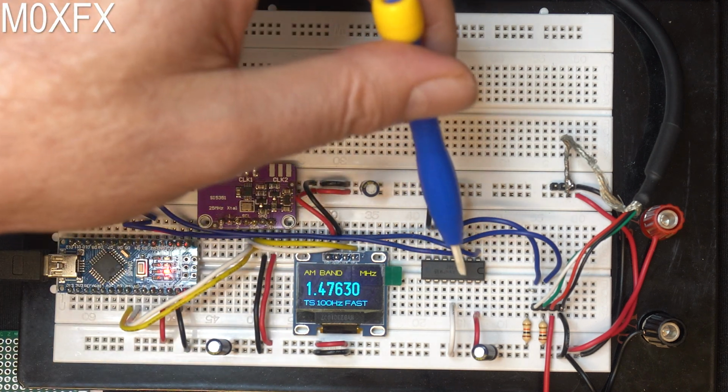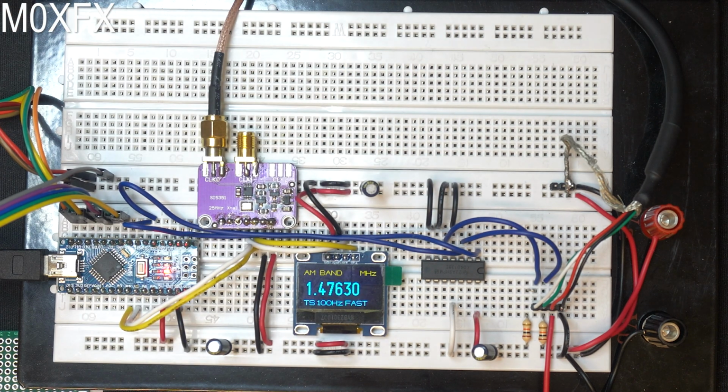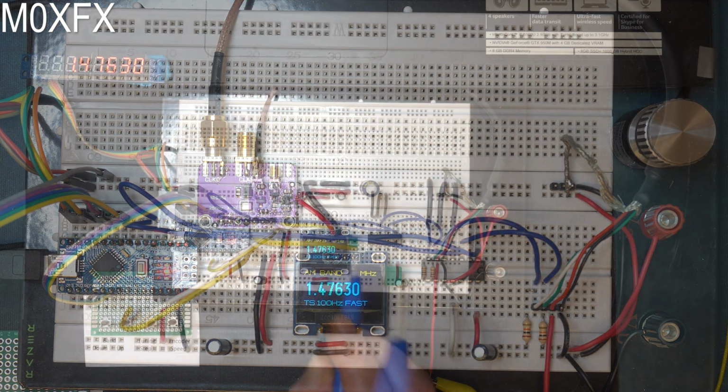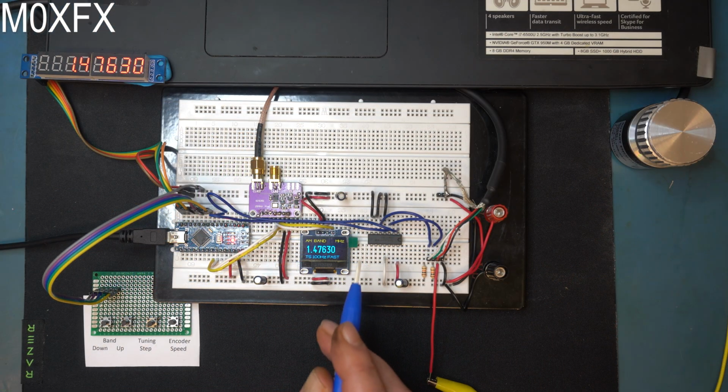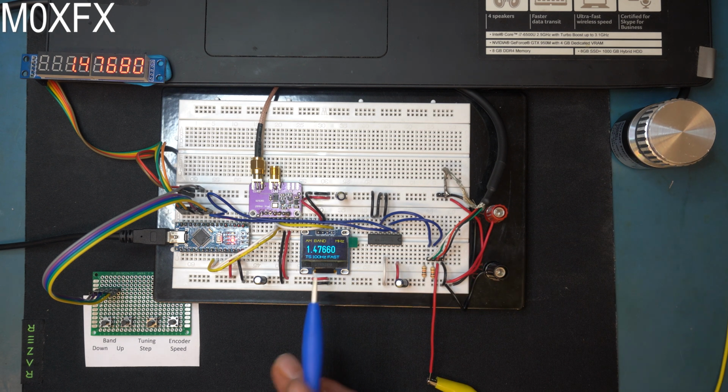We've got an IC on here, which is a CD4013, which is a CMOS device. Very cheap, but it's a D-type flip-flop. And that is, of course, for the rotary encoder. And over here, we've got some switches. So I've knocked this up. We've got quite a few little features on here.